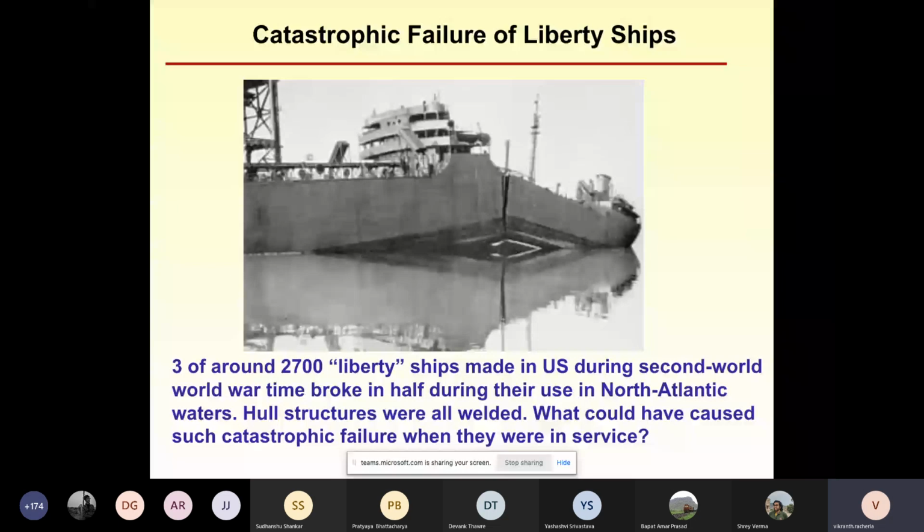People carry it in some small bucket kind of thing, and then someone holds it with a tong, puts it inside the holes, and then they would hammer it from both sides, such that you get a bulb or a round dimple which forms on both sides. And then as the rivet cools from about 1000 degrees Celsius to room temperature, it compresses, and in the process it compresses the two plates and holds them together very nicely. It needed a lot of synchrony and workmanship from the people who would do it.